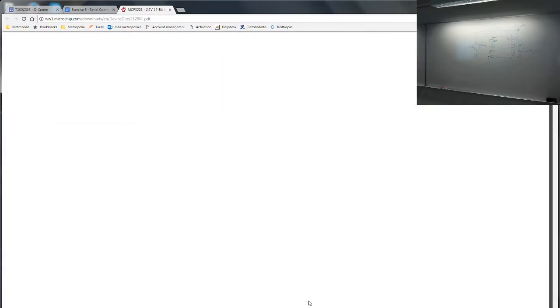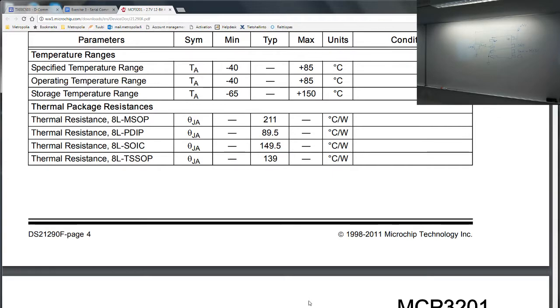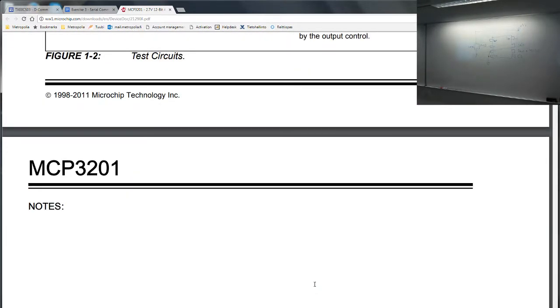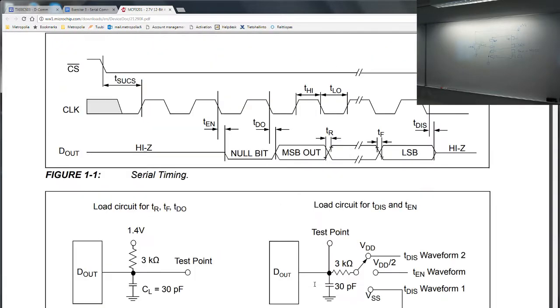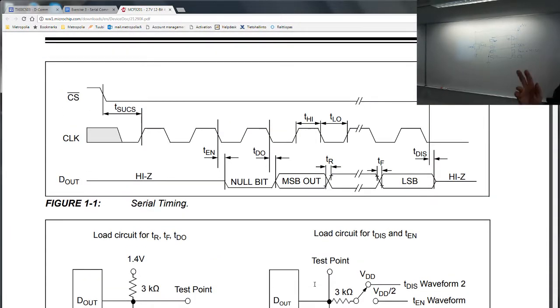And the protocol. The protocol is most significant bit first. Okay. All right, let's take a look at this. So this is how the data is read. When you set the chip select signal down, then you start the transmission. So the first 2 bits that you receive on the MISO line are actually high Z signals, so they can be anything.